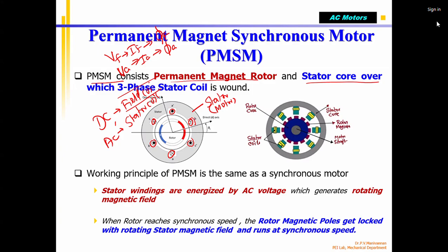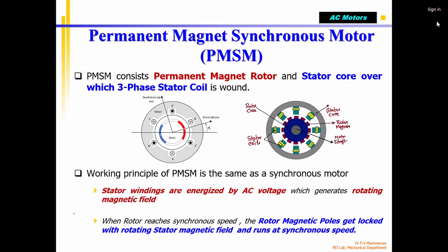That is different. So you need two magnets. Similarly, in AC motors also, you have a stator. It produces a rotating magnetic field. Correct? Then you have a rotor, which is a DC electromagnet. Both get locked and start rotating. Already we talked about the synchronous motor, how it works. This is a permanent magnet synchronous motor. Only it is a synchronous motor.